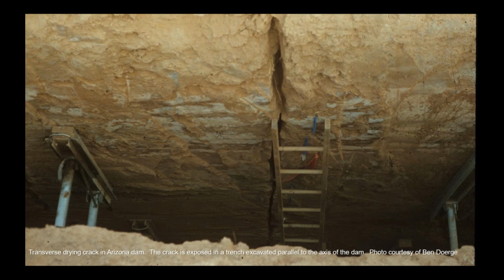Here's some research that was done by the NRCS, where they went in and excavated along the longitudinal length, so the left to right of the dam. And this is a transverse crack, just to see how deep some of these cracks can go. And in this case, it looks like it went down almost the full height of the dam.